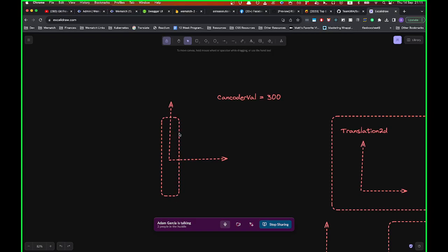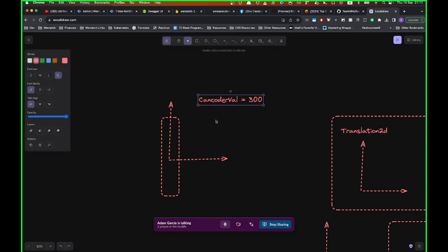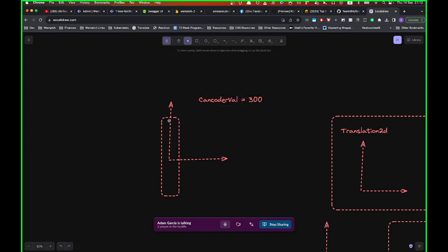One of the steps you're going to have to take is to take these modules and physically face them all front to back, and make sure they're lined up. And then you find what value on the CAN coder is being read. So let's say forward is 300.